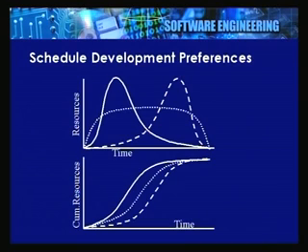This particular curve will have its hump on the left hand side, what is often known as a right skewed curve, indicating that each activity is performed as early as possible and the slacks, if any, are left to the tail end. The graph below gives a cumulative curve for this particular type of diagram. It is a cumulative curve for the histogram that you see on top of it. Now, see what is happening.